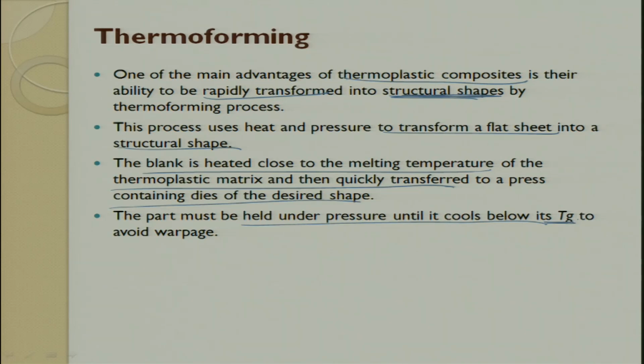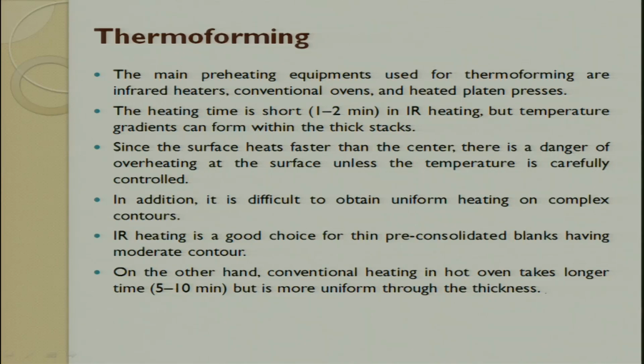If you go back and see, this is what I was trying to explain to you when I was discussing the thermoplastic tape process, the tape winding process, where I was explaining the consolidation cycle. You maintain just below the Tg and then only release the pressure. Almost the heating cycle, whatever we use, will more or less be the same. Here the equipment is preheated, and then the heating cycle is for 1 or 2 minutes.